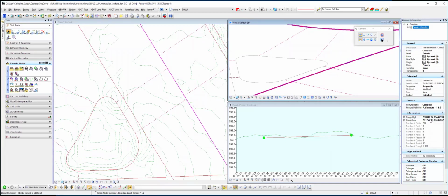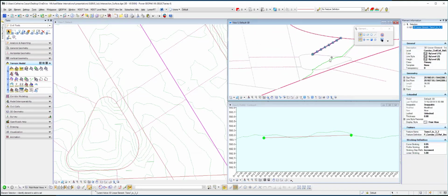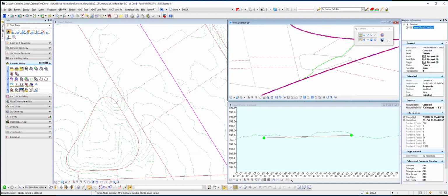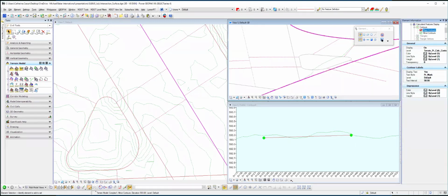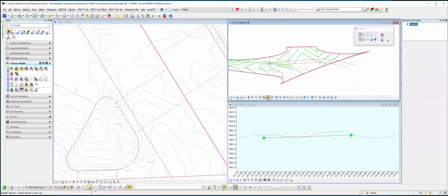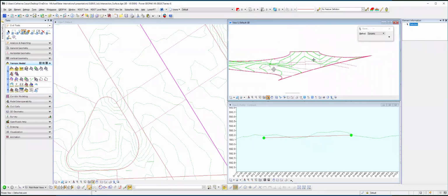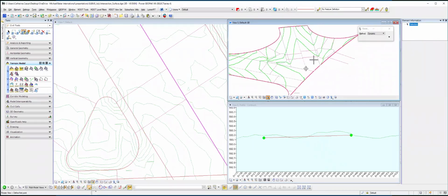And some contours. The contours themselves, what you see in them varies greatly as well. These are controlled here. If you want to see your calculated features of your contours, you can get into them if you want to increase that spacing. Maybe you want 1 and 2, and you can see contours a little more detailed. This particular section is a little bit more flat in nature, so it's kind of complicated to model from that perspective.